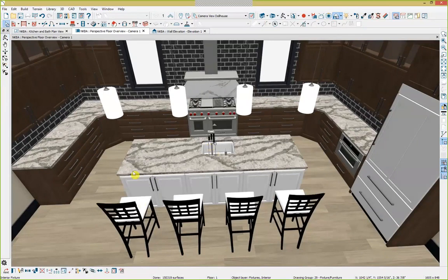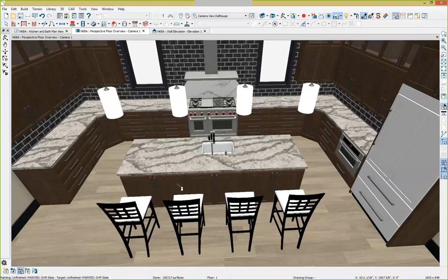So we already learned how to do that once with the material eyedropper. Select the material you want to use, and then you just apply it to your cabinets. And before we do that, you'll recall that we set our distribution mode at the very beginning to be object-wide. We're going to change it now to be room-wide so that when we apply it, it's going to swap out that white material that's on our cabinet anywhere in this room. So one click, all the materials on the cabinet are updated.